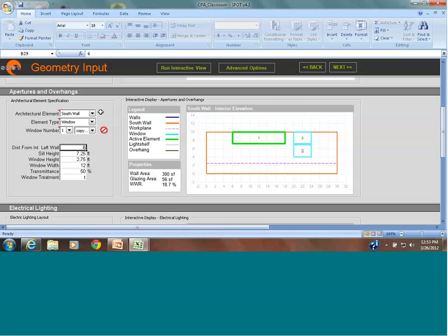So if this report says adequate daylight, then you're achieving visual comfort. And in terms of energy savings, we have to go to that sixth step, and that's where we will place the photocell and figure out how much lighting savings we'll have, including estimated cooling and heating savings.